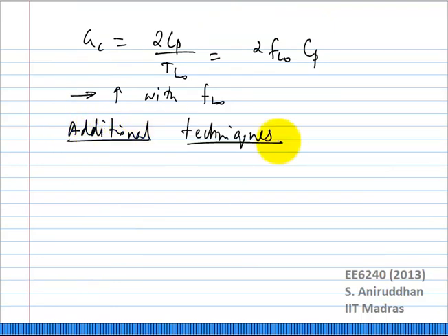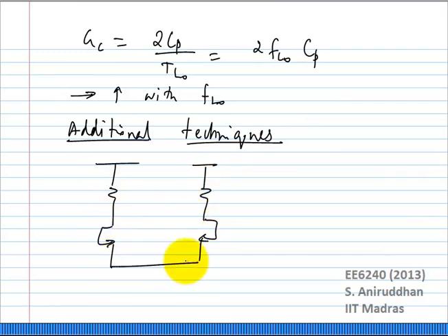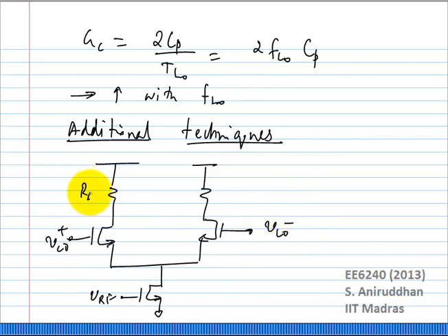For example, let us go back a couple of classes ago. So we had a resistively loaded single balanced mixer. Okay, what was the problem with the resistively loaded single balanced mixer? The problem is that there is a direct relationship between the headroom, the output common mode, and the bias current you are going to use in the mixer. How can you fix this?